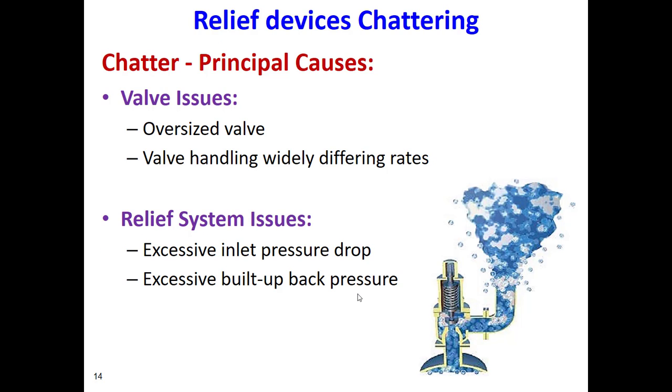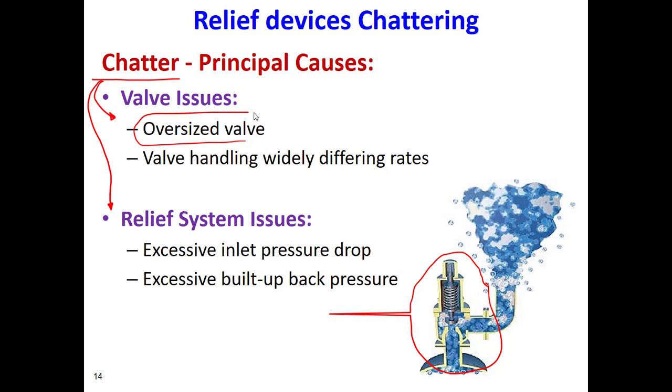Chattering can be due to two reasons: a valve issue, the design issue, and also the relief system issue, where it is installed in the wrong place. As for the valve issue, it can be an oversized valve. We are using a bigger size than what is needed.